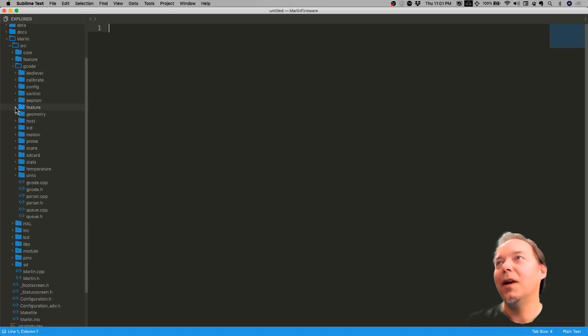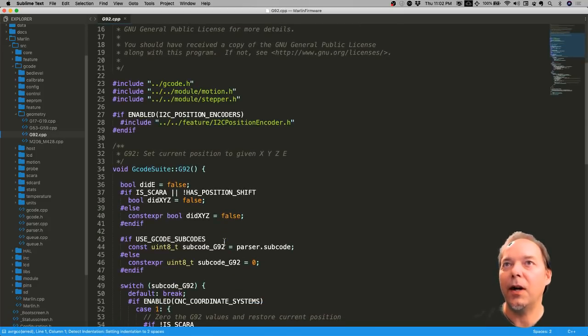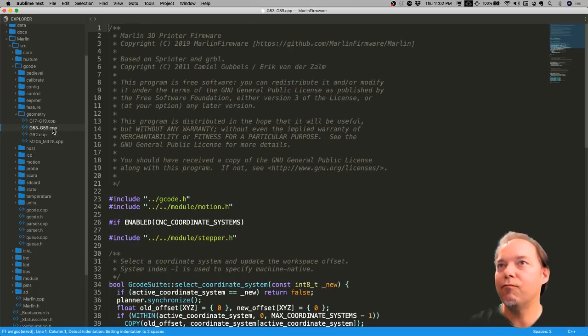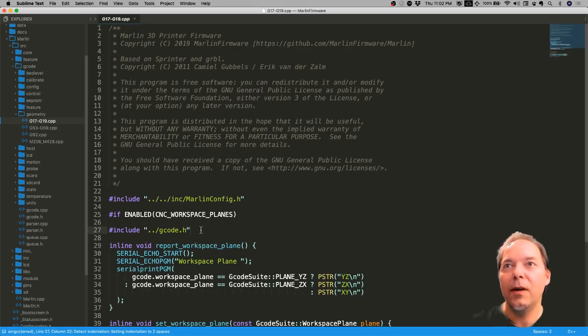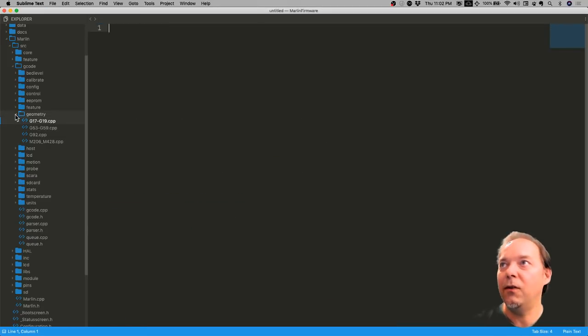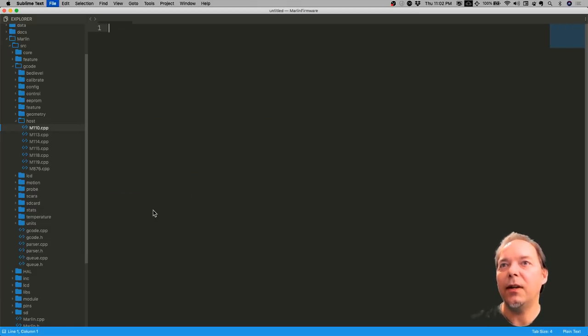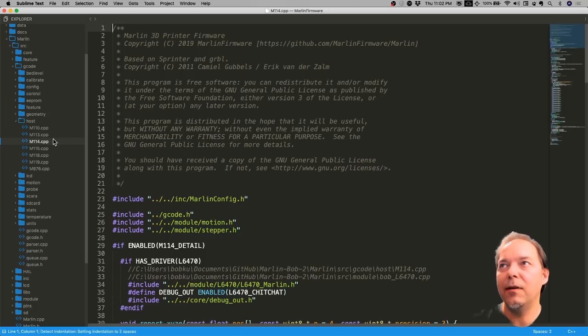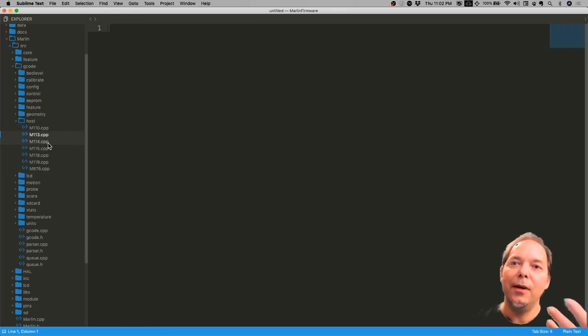Check them out. Geometry, how big is your printer? Set the current position, set the coordinate system, set the home offsets, change your workspace planes, so geometry. Host, M110, set the current line number. M113 is, what is it? Keep alive, yeah. So host keep alive? It sends a message to the host if you're busy, so it knows that you're still there.